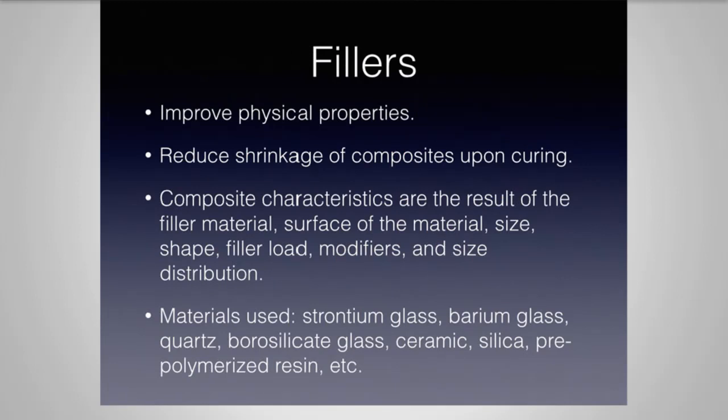Now let's look at the fillers of the composites. Fillers are necessary to improve the physical properties. They can reduce the shrinkage of the composite upon curing, and they help with the overall composite characteristic. Basically, the fillers are going to determine how polishable, how tough, and how wear-resistant these composites are.